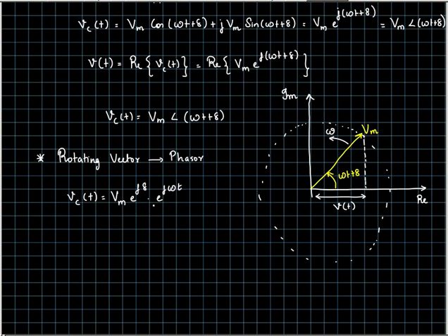And so, because of this redundancy of the term omega, when representing this phasor quantity, it makes sense to omit the omega information, and conventionally therefore, the phasor is represented as a time invariant complex quantity by removing the e raised to j omega t part, and it is then represented as Vm e raised to j delta, or in polar form it is Vm angle delta.